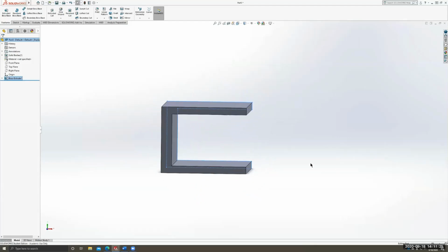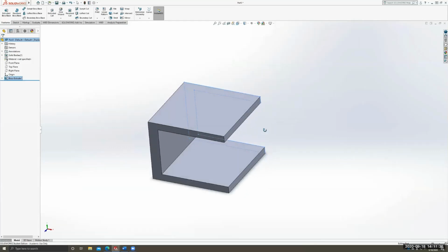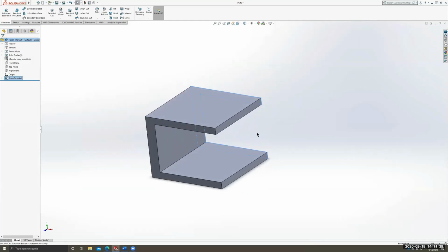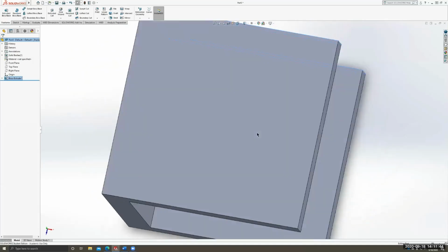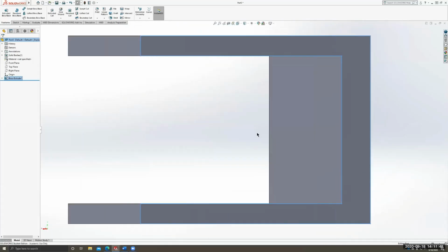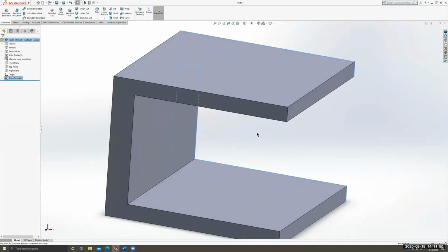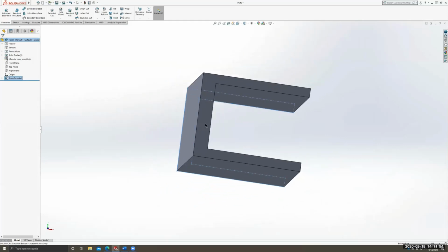How did you get it to orbit? Orbit? Do you have a mouse? Yeah. Okay, do you have a scroll wheel? I do. Okay, so just hold down on your scroll wheel and then you can just drag around the screen. Okay. And also on your keyboard, if you hit Control and then hit the numbers 1, 2, 3, 4, 5, 6, 7, 8, you can go to different views. Oh, wow. Okay, nice. I think Control 7 is your isometric. Okay, so let's do this view.